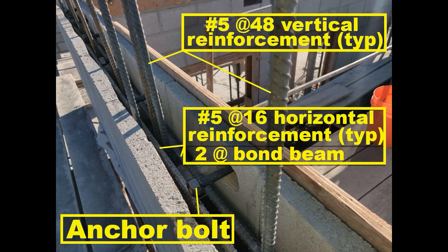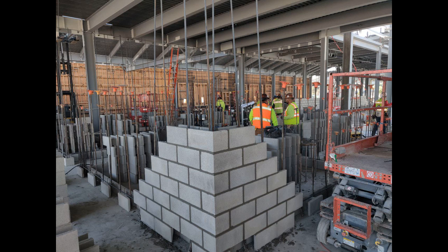Inspector to verify grade and type of reinforcement, anchor bolts, and pre-stressing tendons and anchorages. Size and location of structural elements is in compliance. Also preparation, construction, and protection of masonry during cold weather when the temperature is below 40 Fahrenheit or hot weather above 90.